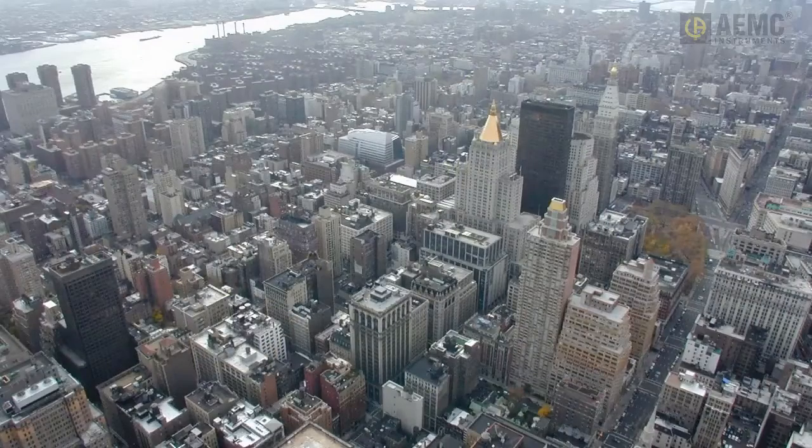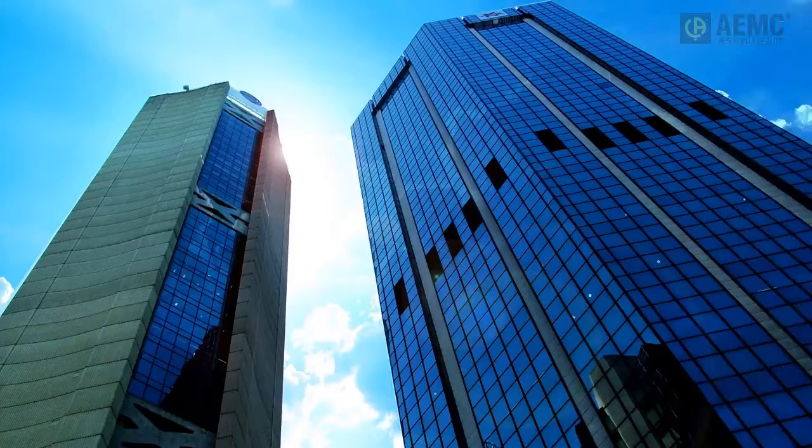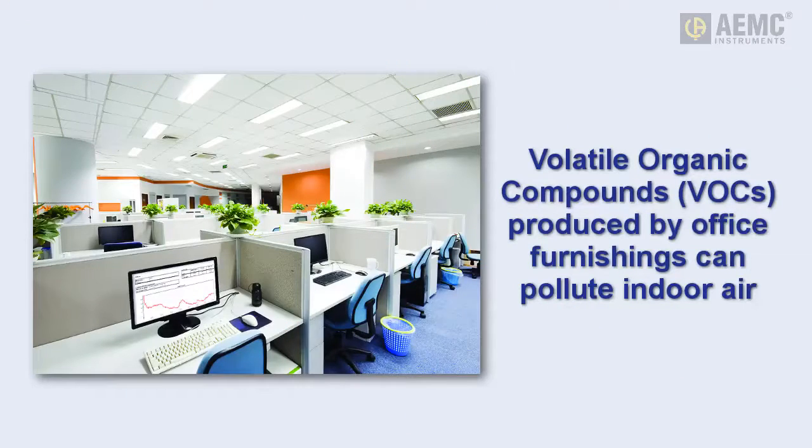In many large cities with serious or severe air pollution, office buildings with sealed windows are now the norm. Unfortunately, this often creates an indoor environment that degrades air quality. When unfiltered indoor air is continuously recycled without exchange with fresh outdoor air, volatile organic compounds emitted from furniture and carpets can raise the level of potentially dangerous pollutants in the air. These gases, combined with the carbon dioxide we exhale, can make occupants less alert, productive, or healthy.